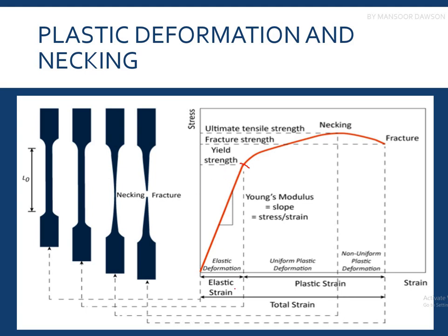Okay, so what is happening in the elastic region? This is our specimen, and if we apply the load, the length increases, but it would come back to its original position when the load is reduced or unloaded. But when we increase the load in a tensile test, or when we increase the stress, there is permanent deformation going on. So the strain now would be permanently retained in the specimen.